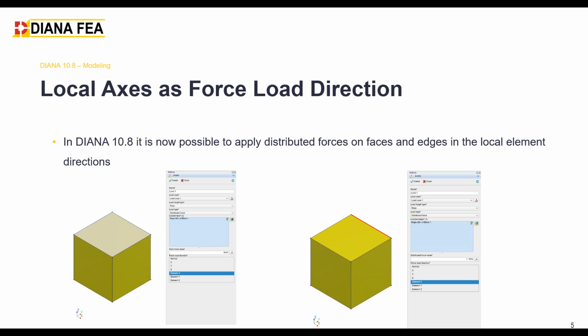Another new feature in 10.8 is the possibility to apply distributed forces on faces and edges, considering the local element directions as the direction of the load. Previously, up to Diana 10.7, it was only possible to consider normal and global direction as the direction of the load. Now you can choose between the element X, element Y, and element Z direction for the load direction.